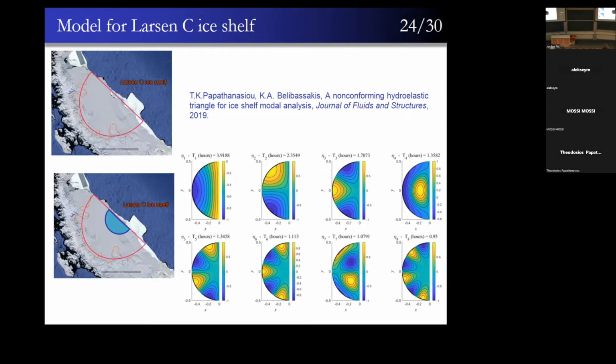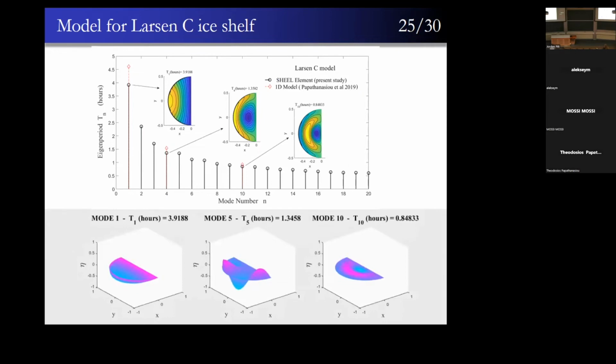Several mechanisms might have contributed here, and there are several analyses by authors, but mode 4 looks a prime suspect, as well as mode 5, which produced in about 1/3 of the span high deflections and moments. Number 4 is a normal moment, number 7 is a twisting moment, actually. Now, these are some movies of the first, 5th and 10th mode. How do they look here, compared with the 1D model in a transect at the center of the ice shelf.